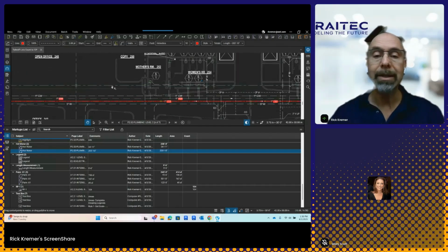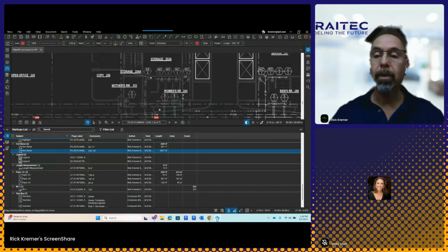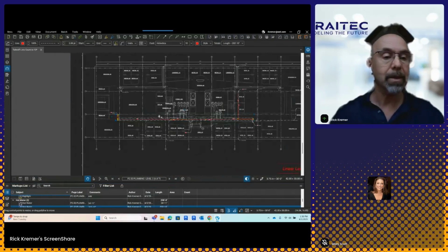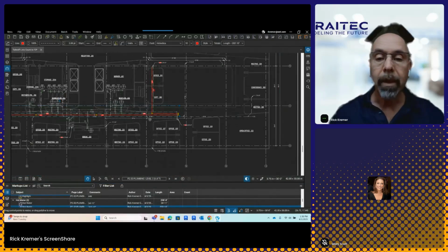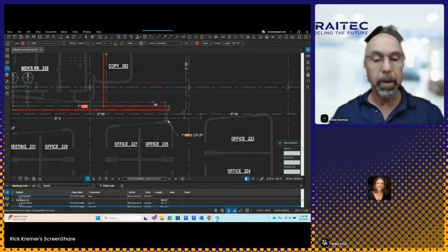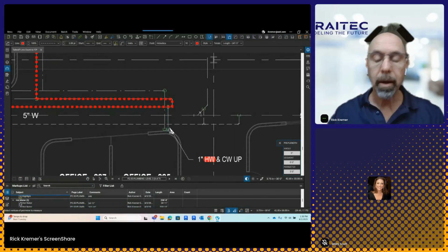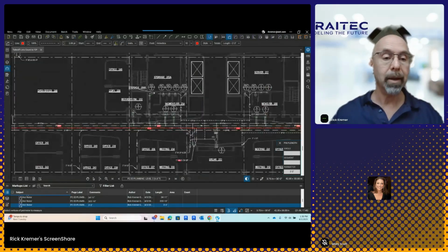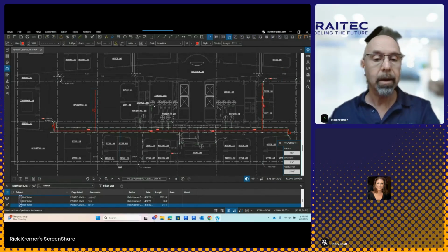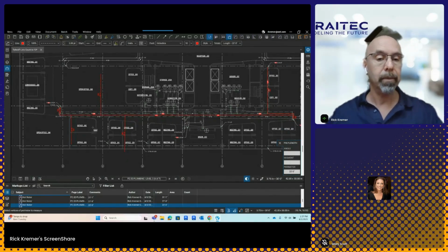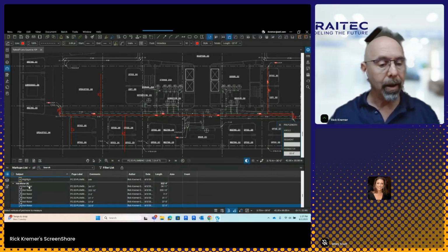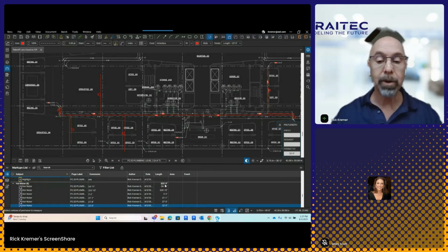So what I can do is, let's say for argument's sake, my hot water line from here is also in another area. Remember, I'm looking for the highlighted areas. And I think oh, there's another hot water, right? So it goes over here. So I type in number 1, and I'm going to tee off from here to here. Let's say for argument's sake that that also teed off from here to here, and here to here, and here to here, okay? Like branch runs. As I keep doing that, the total length right here shows me my total length of 322 feet.